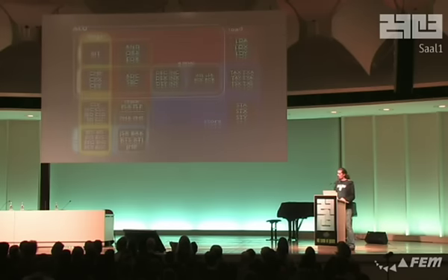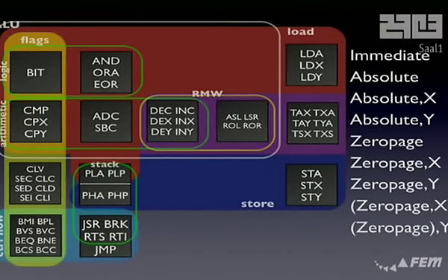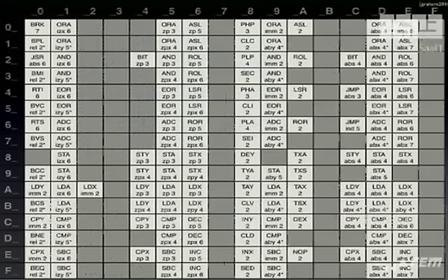That's an interesting thing. Looking at all the instructions that we have and all the addressing modes that we have, if we combine them, if the CPU were completely orthogonal, being able to combine every general purpose operation with every addressing mode, it wouldn't fit into the 256 different opcodes. So what they did with the opcodes is only encode the ones which really make sense, the ones which are most interesting, most important. So only about 60% of the opcode space is used. And the rest is just, well, they say it's undefined.